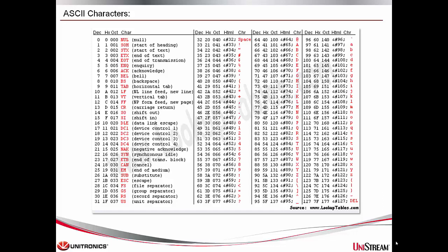Different devices may use certain ASCII or hex characters to indicate the start or end of a message. A checksum or a CRC can also be utilized for each device, which adds a generated code to verify message integrity. Checksums can also be helpful to reduce any electrical noise or irrelevant data that is not accepted by the PLC.